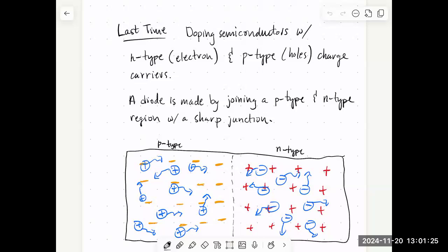So this is a drawing of an N-type doped piece of semiconductor. These pluses represent the dopant ions plus their core electrons, and they have a charge of +1 relative to the silicon ions. If on the other hand we chose a dopant that had 3 valence electrons, then those 3 electrons would participate in covalent bonds, but there would be one missing electron, or a hole, and we also viewed these holes as being able to move around throughout the material.